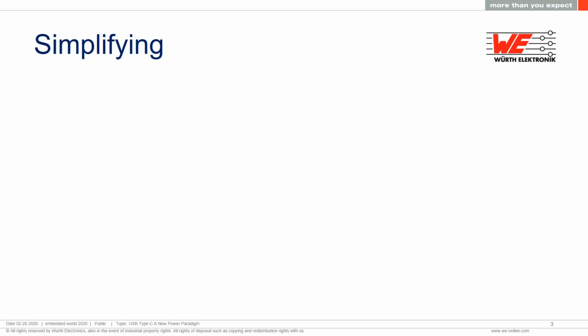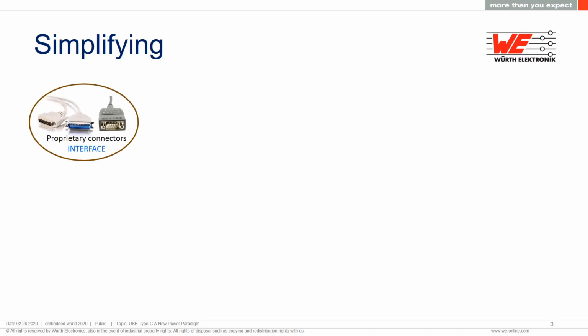The whole idea of a universal serial bus, USB, was to simplify connections made to personal computers. In the early 80s, when they first came out, they had a wide variety of connectors. You had everything from DIN connectors for the keyboard, DE9 connectors for the mouse, DB25 connectors for serial ports, and then using the opposite polarity DB25 for the printer port, matched to a Centronics connector at the printer. They were all large and they all required their own software drivers.